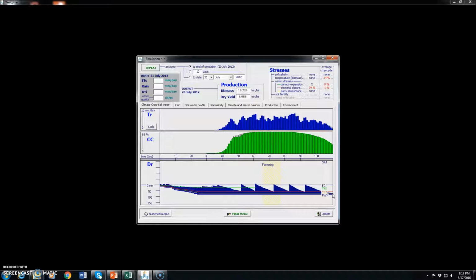As we said, if we apply on an average 61 on every irrigation, there are places in the field that will only receive around 30 and places in the field receiving around 90. This is due to the uniformity of the irrigation system.